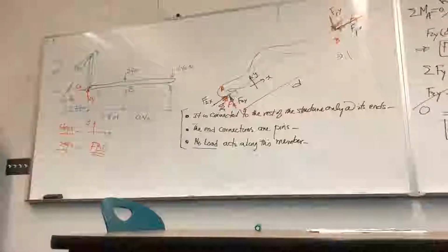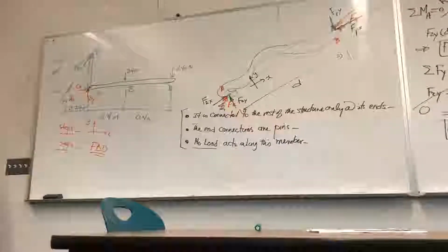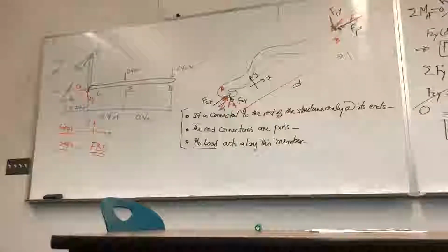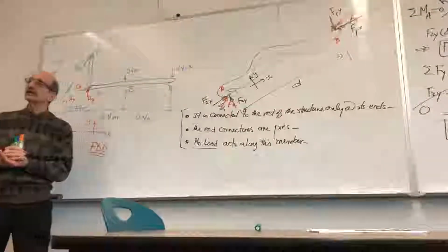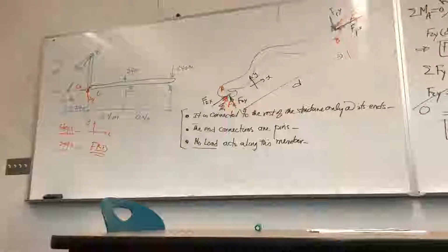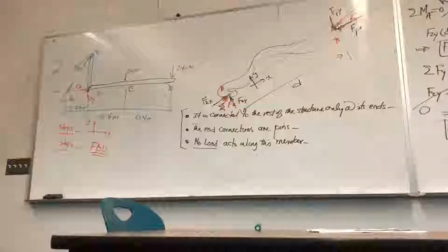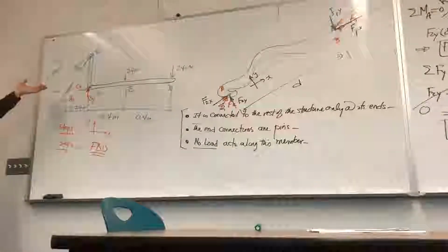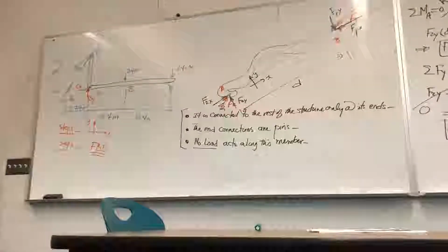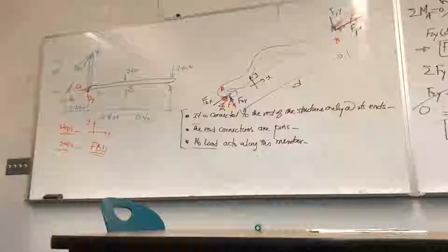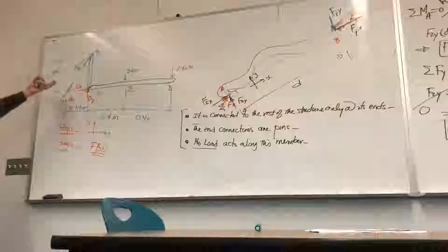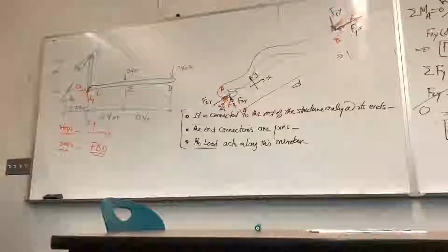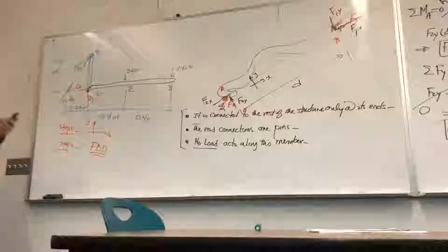This is a concept that you really need to remember and be good at, because as you will see, all the structures that we will be studying later, trusses, frames. In the case of frames, you may have frames that have several two-force members. In trusses, every single member is a two-force member. So you really need to learn this by heart, and you will become very good at it. So now the problem is easy, right? We can move on to step 3.